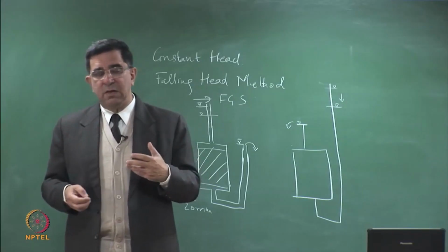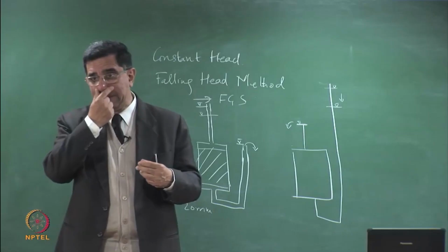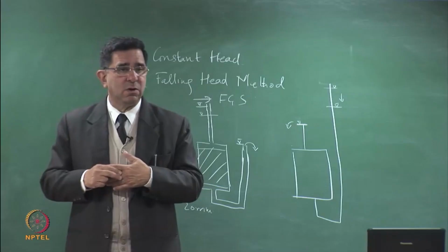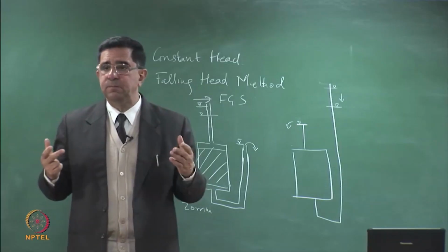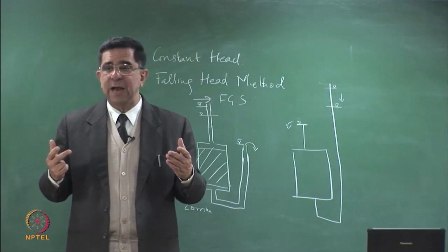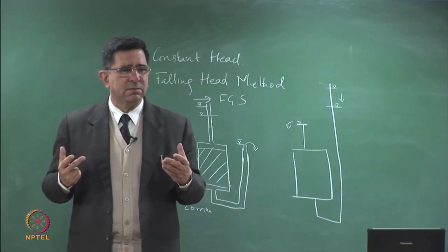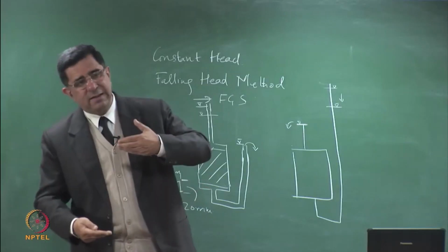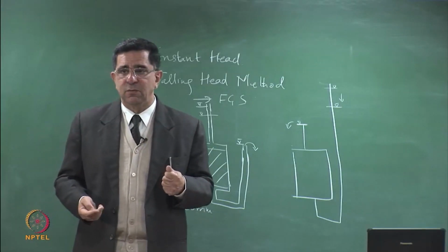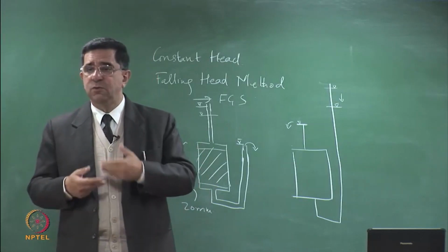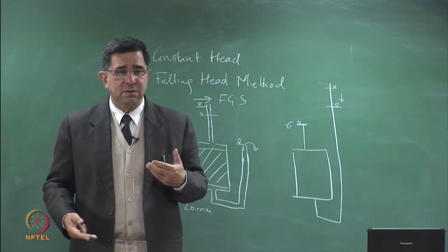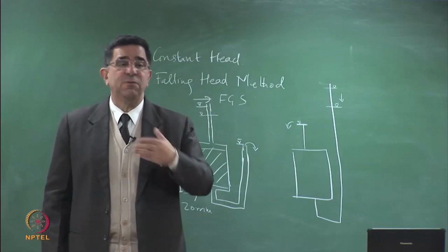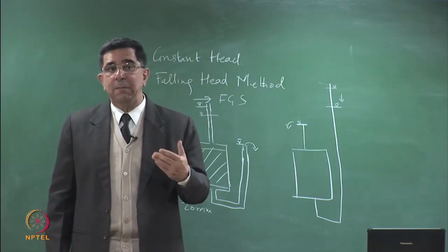And in clay, you remember there is a capillary fringe. In clay, if you have a groundwater, then a capillary fringe is formed above the groundwater. Do you remember the magnitude of this capillary fringe? How high can this capillary fringe be? Few millimeters, few centimeters, few tens of centimeters, few hundreds of centimeters. 10 meter is huge, but a few meters. So you can have capillary fringe a few meters.